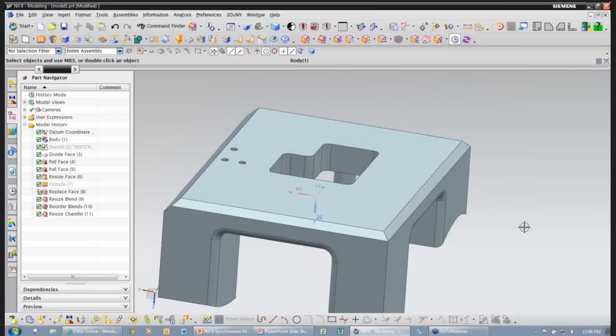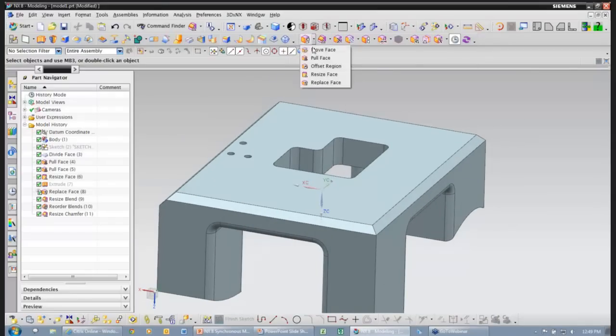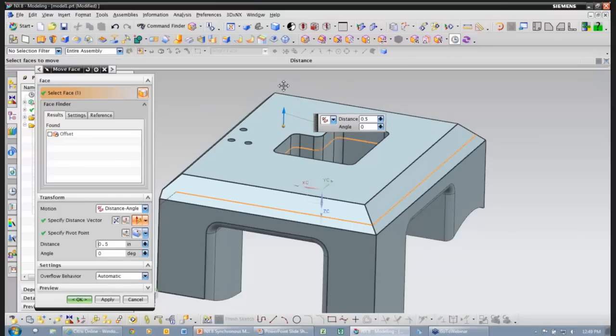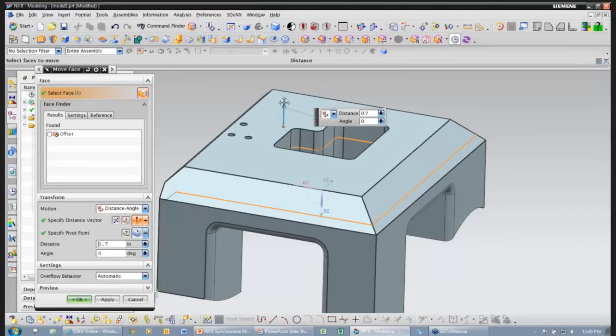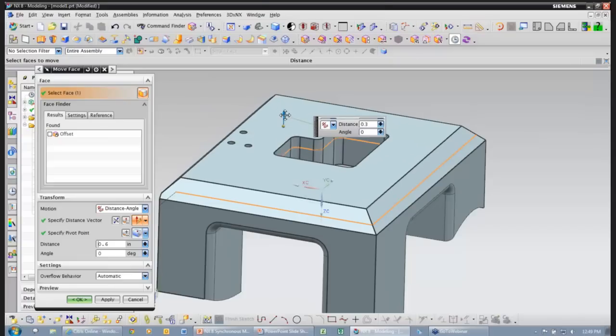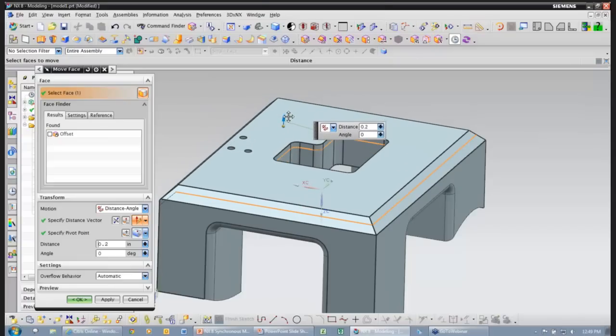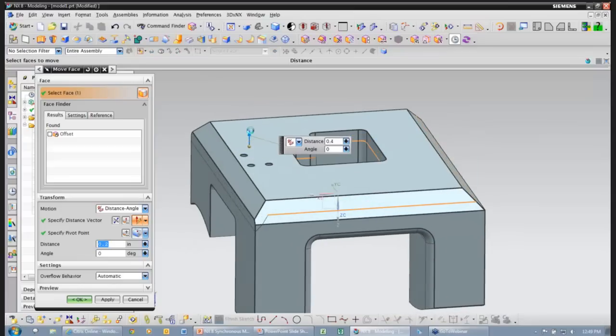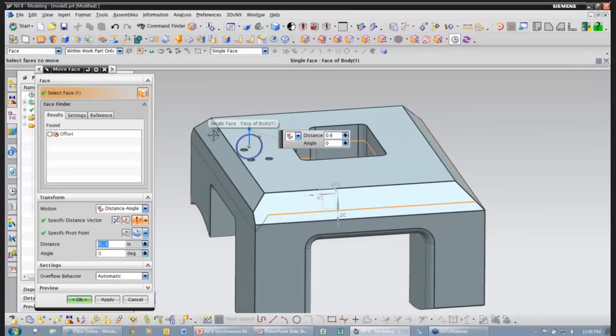Now, where does the label chamfer come into play? First of all, before we look at the label, if I select this face and I just want to move this face up, notice how the chamfered face is not maintaining. We brought this in from a neutral format Parasolid, so it doesn't really know that the face is a chamfer. The one on the left side is a chamfer because we just got through resizing it, so it knows it's now a chamfer.